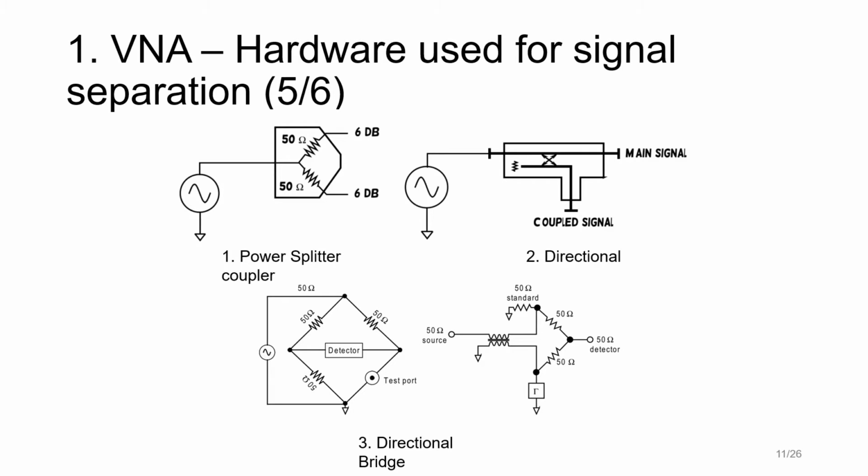However, owing to the difficulty of making very broadband couplers, directional bridges are often used. Bridges can operate over a very wide range of frequencies, but they exhibit more loss. They work by producing signals that are proportional to the mismatch of the device connected at the port with respect to the nominal port impedance, which may be about 50 ohms. The diagram shows all branches to be around 50 ohms, but if we want more power available to the test port, the resistance on the other branch can be increased. It's a design choice for the person who's making the VNA.